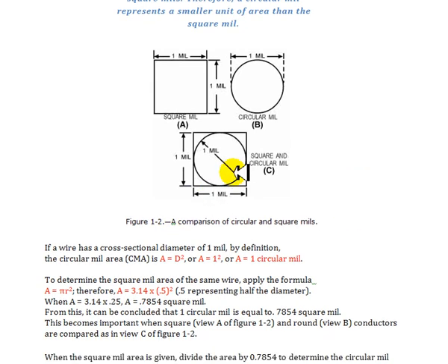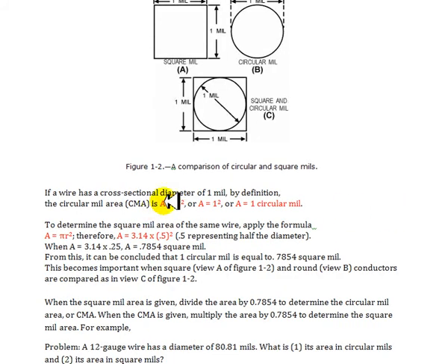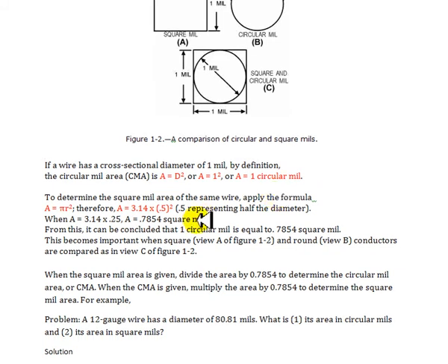So it depends what type of wire you use. It could be a long piece of copper wire that's square that you're using. You want to know the resistance of it. Then you use different formulas. As you can see, for square we're going to use A equals D square on our chart. For circular, here's A equals pi times R square, the radius squared.